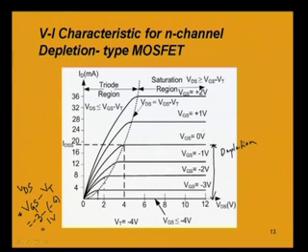So, drain to source current is increasing, and this will be continuing if we go on increasing this gate to source voltage in a positive direction, say 2 volt. So, the drain to source current will be increasing and increasing. So, in this region enhancement phenomena is occurring.